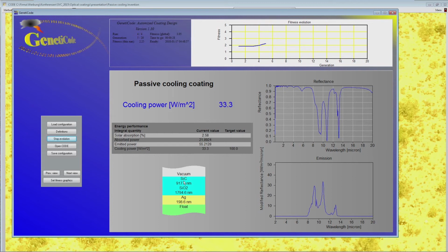Okay, I guess if you think in terms of solar cells, with 1 square meter you will get something like maybe 120 watts. They have an efficiency of typically 10 to 12 to 14%. So if you would have an electric power of 100 watts per square meters or 120 watts, and you would drive a refrigerator or the air condition inside, maybe the cooling power would not be much higher than this.